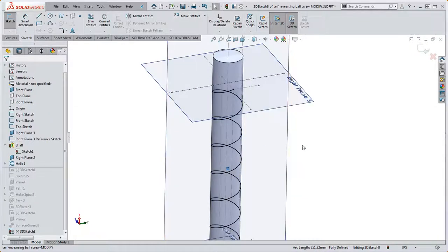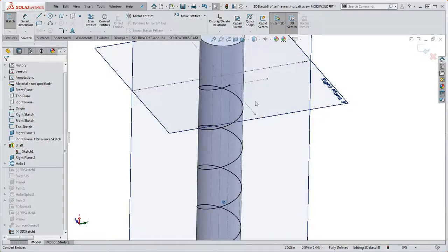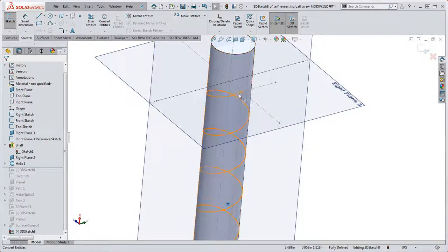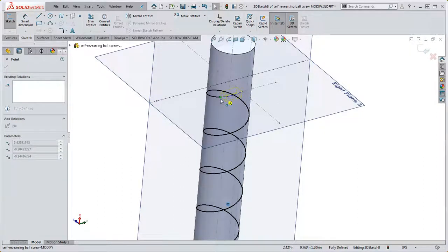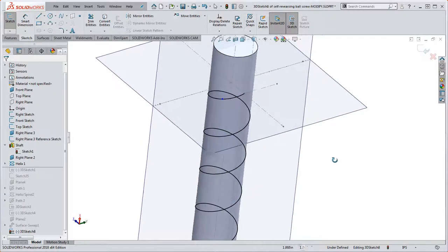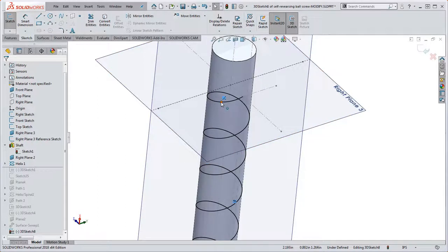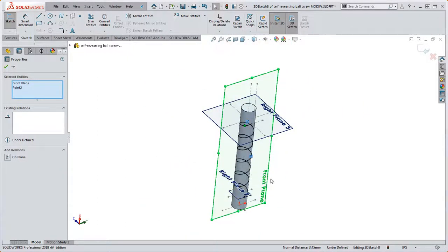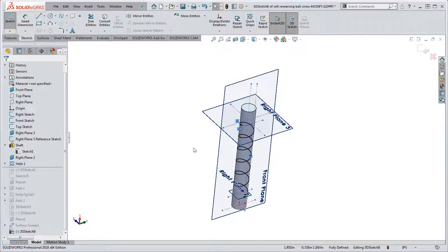But if you go to the green check mark, now we have sketch geometry in here which emulates that helix. What's not really defined in this sketch geometry is the endpoint of that 3D sketch line. So we're going to take that endpoint and drag it back a little bit. I believe it created a coincident relationship with the surface over here, which is okay. But we want to take that point and that surface over here, this plane that I highlighted, the front plane, and make it on plane. We're going to put it right on that plane.